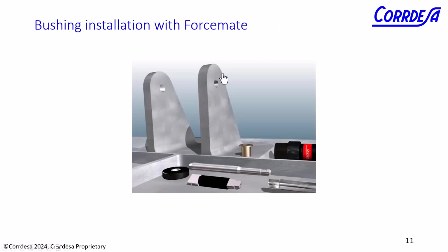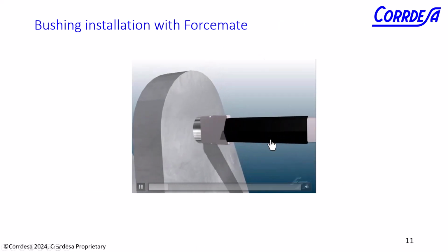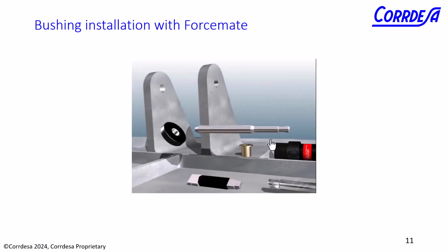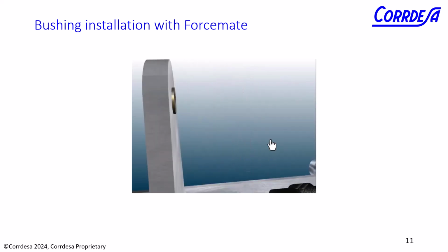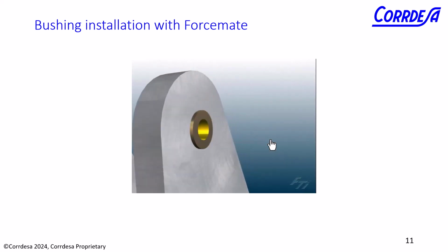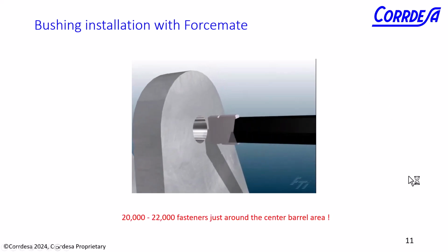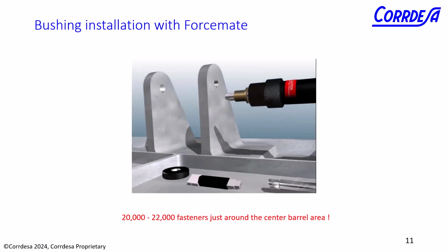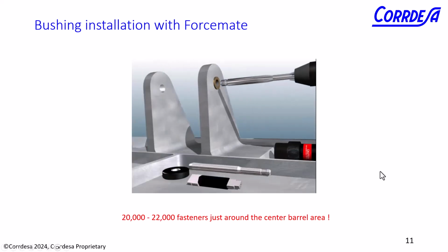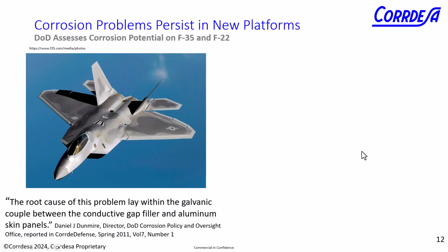Certainly around bushings, we'd have to remove the corrosion and then somehow bring that hole back to dimension. If this is for fasteners, you put that bushing in there, and you can cold fit it into there. So it's important what materials those bushings are made of, because you're going to start a new interaction there. There are a lot of fasteners, so you don't want to be doing this process for each and every fastener. So you need to make material choices, coating choices that can avoid this.